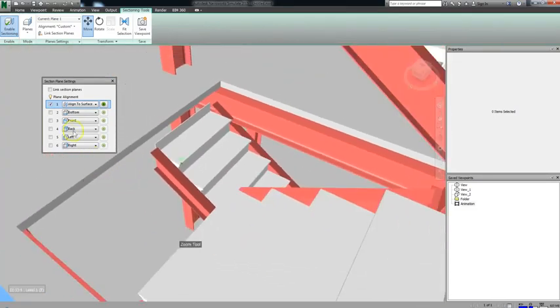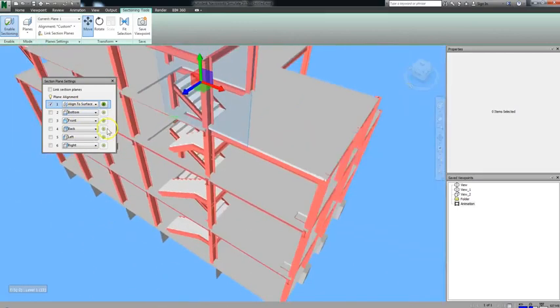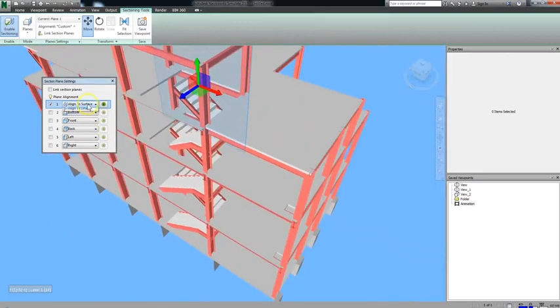This can be useful if there is a particular element in your model that you want to base your section off of. The final section mode is Align to Line. When you select this mode, you're able to draw a 2D line that you can then attach your sectioning plane to. This way, if there's no other option available to you that will accomplish the section that you need, you can still accomplish your goals. Remember, if you want to turn off sectioning, just click the Enable Sectioning button.